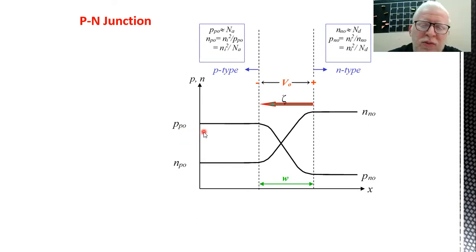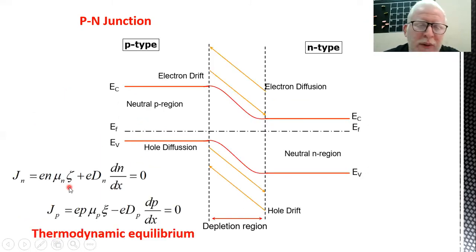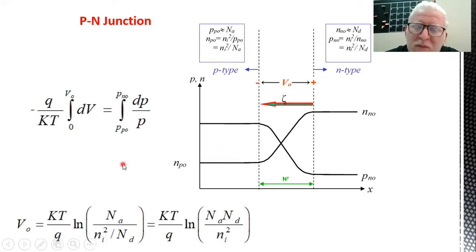Similarly, you can also name all the other 3 terms with the same terminology or procedure. And herein, using this equality equation, we reached an expression for what we call the built-in potential inside the junction. It's built-in because this is a natural potential created due to merging the p region with an n region, and we found that this built-in potential is proportional to the temperature of the material, the doping concentrations N_A and N_D, and of course the material itself, which is the intrinsic concentration, or n_i.